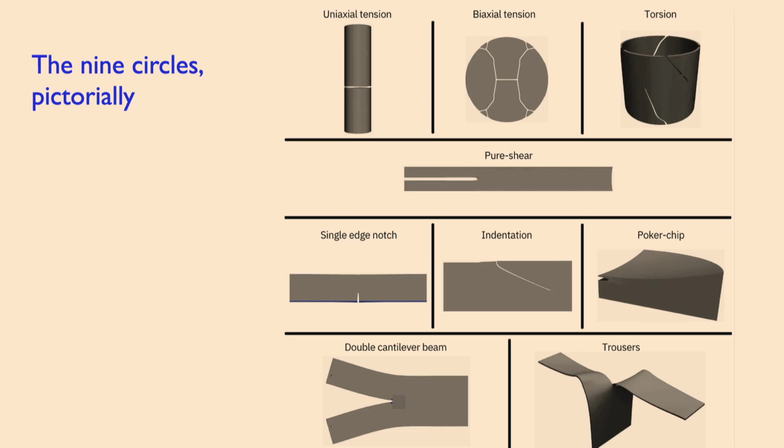I don't care too much about that, but if you're setting epsilon as a material parameter, you have to admit that you're not using a regularization of any sharp model, right? But what I liked about the idea introduced by Eric Lorentz was here was a way to essentially isolate the regularization length from the apparent effective uniaxial tensile strength that the model will give you, right? So that you could think about lowering epsilon, which is useful in lots of ways, right?